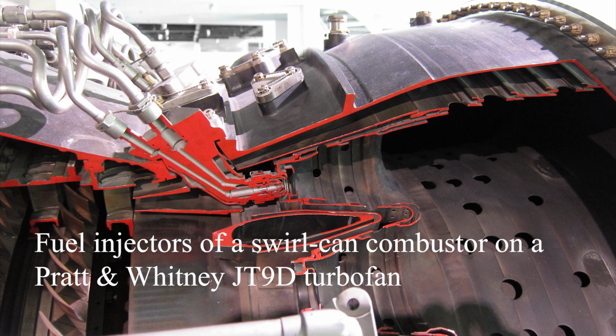Most igniters in gas turbine applications are electrical spark igniters, similar to automotive spark plugs. The igniter needs to be in the combustion zone where the fuel and air are already mixed, but it needs to be far enough upstream so that it is not damaged by the combustion itself. Once the combustion is initially started by the igniter, it is self-sustaining, and the igniter is no longer used.